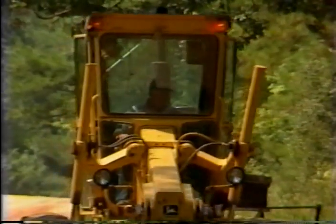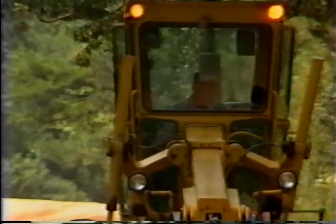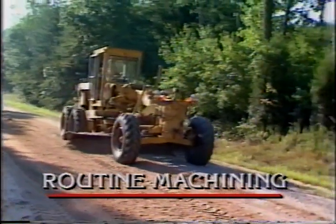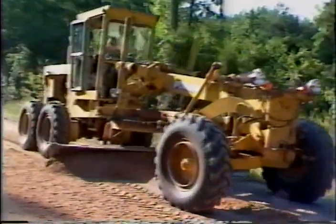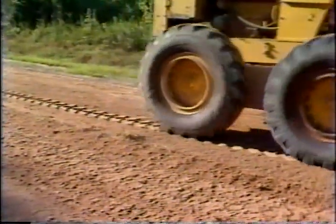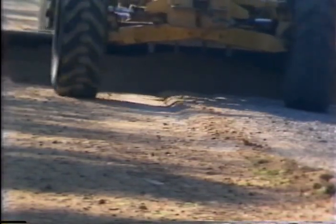Now, let's look at the basic maintenance procedures for gravel roads. The first operation is the routine machining of gravel roads. The objective of routine machining is to recover the aggregates from the edge of the roadway and redistribute them back across the road. This is accomplished by the dragging and smoothing action of the blade.